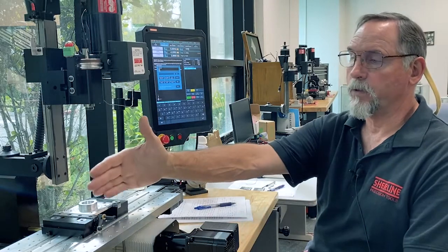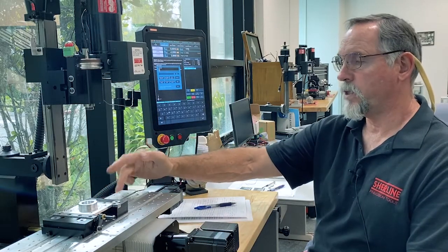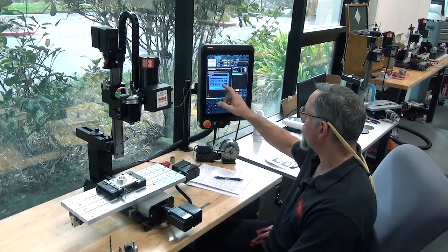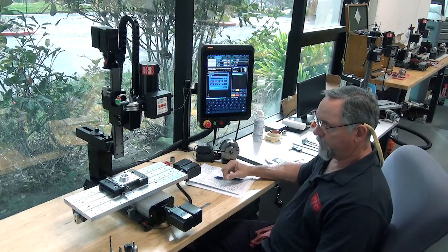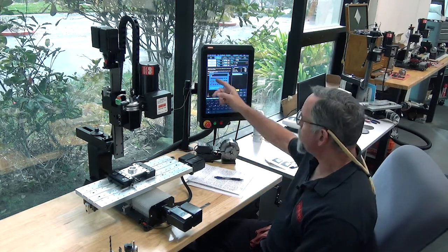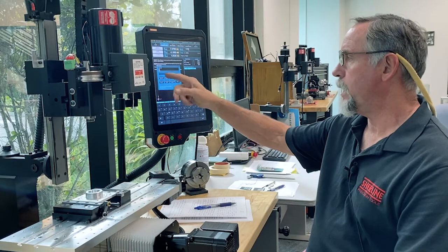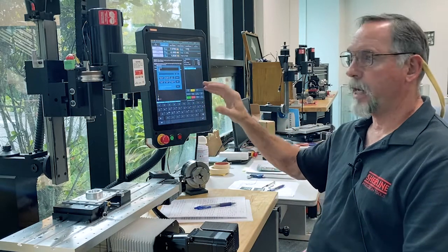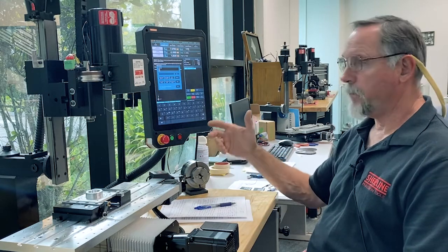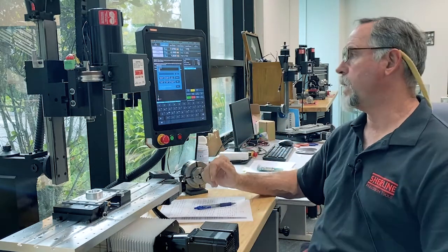Like again, whether it's the part 0 position or the tool center position. So right now it's set up for the part center line. I'm just going to hit park position. And it just goes there. The other option is to go into your MDI and type in G90, G00, X minus 7.087, Y minus 3, and so forth, which takes a lot of time.